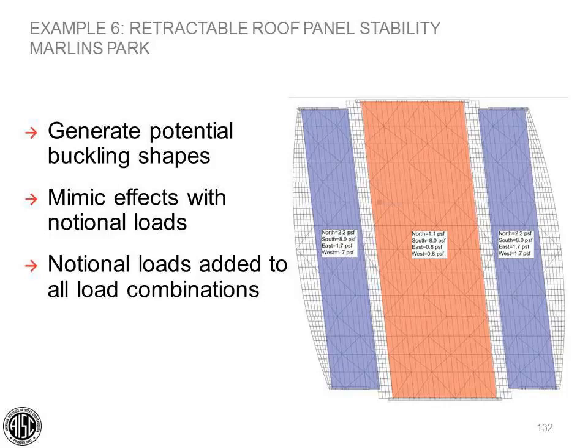That's a great question. So the moments that you get out of your analysis are what you should be using for designing your base plates and anchor rods and foundations. The notional loads are really fictitious loads that we're applying to create that displacement. So the moments that result are valid. The shears, however, if you wanted to, you could subtract out the notional shears that you added into your system. Again, those are fictitious loads.